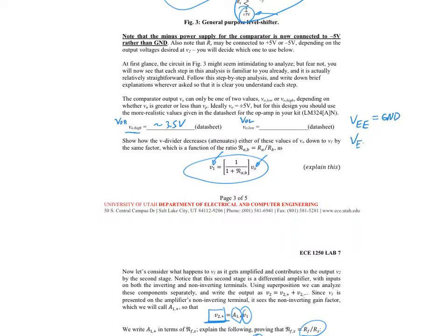So what about when we have this at negative 5 volts? And by the way, in this case, it's going to say VCC is 5 volts unless otherwise noted. So it's actually quite simple for this part here, but for this part, it isn't as straightforward. So it's easy if you just use kind of a hand-wavy argument and say, well, when we have this condition, and we're always considering this condition, but if it's this condition here, then it gives us VO low equals, I think it's like 5 to 20 millivolts.